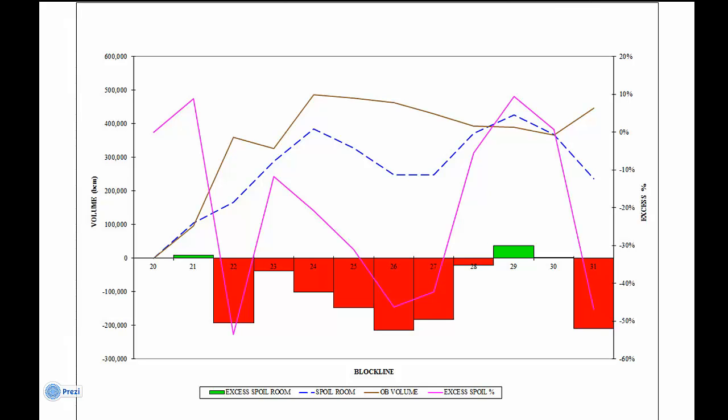If the spoil fit is tight, for example, do they assume the dragline carries the spoil along the strip length, or maybe they reduce the dragline volume by taking additional pre-strip in certain blocks? Or if the spoil fit is plentiful, do they raise the dragline horizon to take advantage of the spare spoil room? This, however, also impacts coal uncovery. The process is usually iterative, as the spoil fit dictates the dragline horizon, so it's important to get the design as accurate as possible.